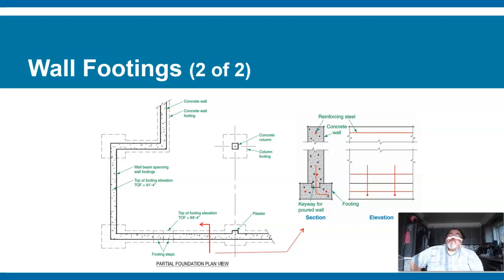And this stem wall is where you would pour in a second pour. You'd pour this first guy, and then later put a set of forms, and it shows you it's broken here because the stem wall can be really tall. And on one side it could be under the house, the other side the dirt might be all the way up near the top, supporting the dirt away from a sloping hill. So that's why it's broken here, because it's saying it could be any length and height.